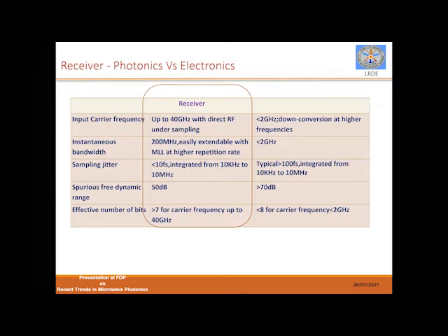They are using an MLL, mode-locked laser, for the transmitter and receiver section. And you all will agree that rep rates up to 10 gigahertz are easily available in MLLs. So that means if electronics doesn't have limitations, we can go further.